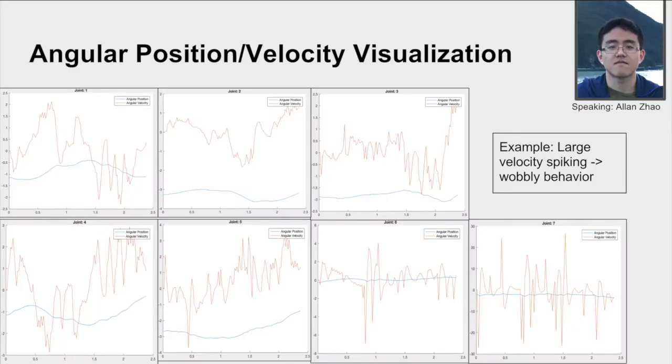In addition to our simulation animations, we also plotted joint states and used these graphs to inform us more quantitatively about the effects of our tuning on the behavior of the robot. For example, in many of the simulations of lower costs on velocity or input torques, we were not able to easily quantify how poor trajectory following was just by looking at the animations.